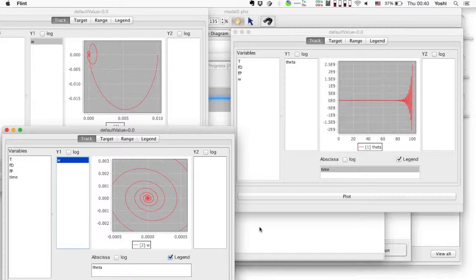Because of the time delay, the neural feedback proportional to theta, whose gain is p, becomes 0 after the state overran the upright posture. Then the system tries to draw back the state to the upright posture, but again the state overruns. When the value of p is large with respect to the delay, the amount of the overrun becomes larger and larger each time the state overruns the upright posture, and finally falls down.